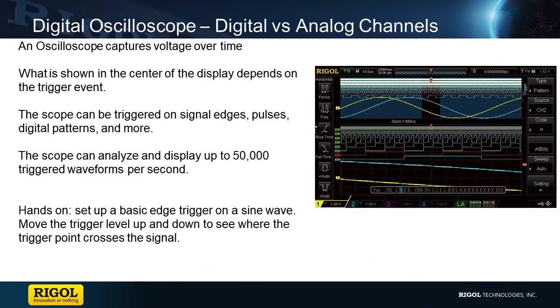And then the other thing to know, we won't do too much with the digital signals today, but about these scopes is you've got the digital connector at the bottom, which really allows you to capture bus signals. So you can capture digital signals from a computer bus, I2C, SPI buses as well, and look at those signals and their timing in comparison to the analog signals.